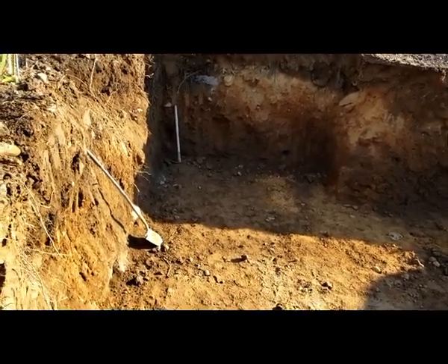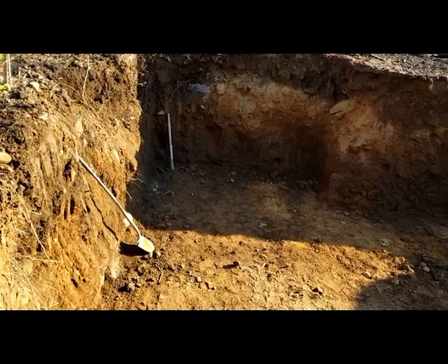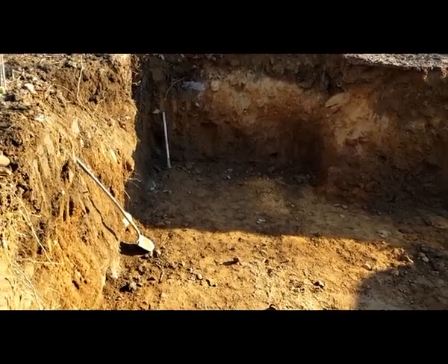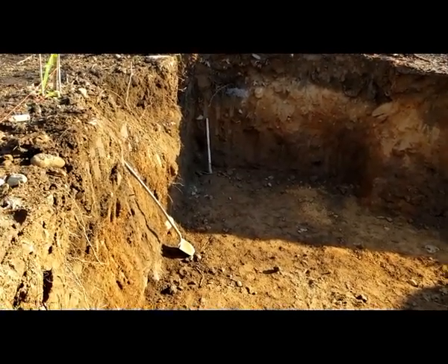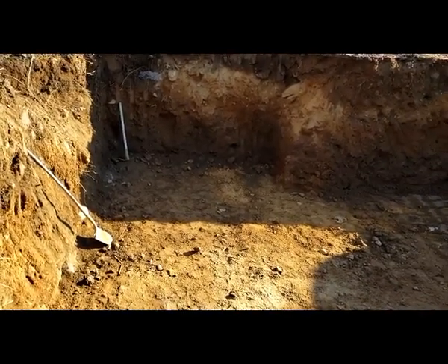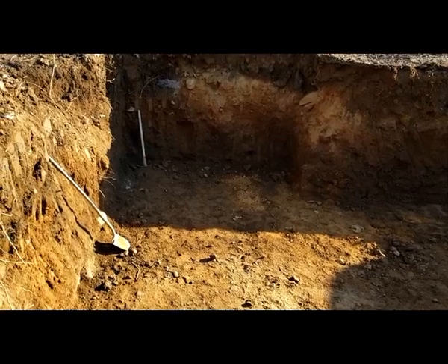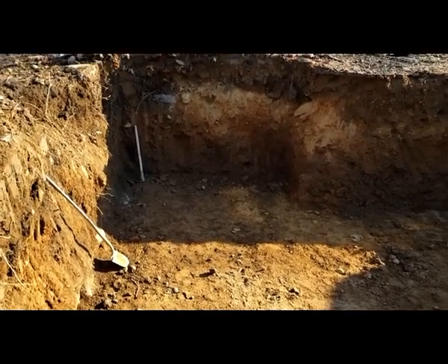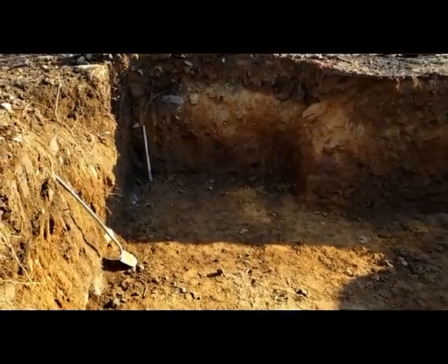At this house, we're doing 6 inch under the footing. We're gonna have a layer of stone. Before we even put the stone, we do a compaction with a 200 pound walk-behind compactor. We're gonna compact the soil, put the stones, and compact it again. Then we're gonna start doing the footing.